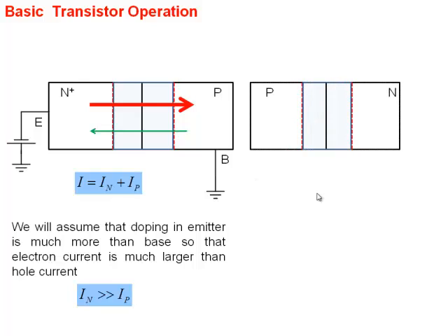All right. I take another PN junction here. So till now, it's only a PN junction here. And I take another PN junction. And this PN junction, base, it's only a P. I'm only calling it base for a moment. So it's grounded. And collector is connected to positive bias, which means it's reverse biased. This junction is reverse biased here, which means that the current that would flow would be very small.